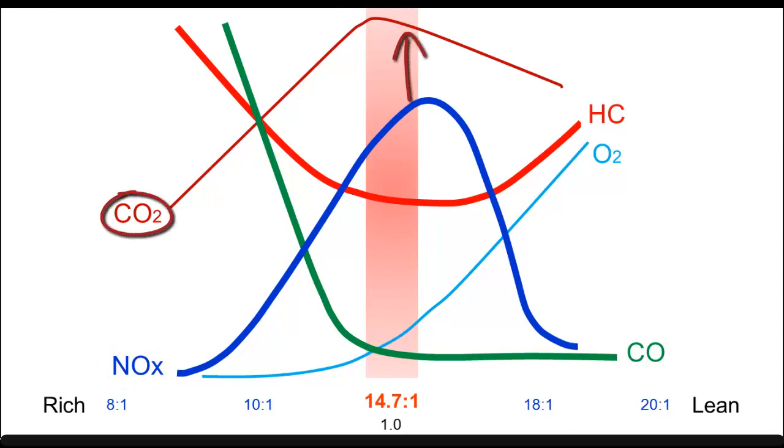This combustion indicator signals near stoichiometric mixture. Oxygen at 2.22% indicates slightly lean of stoichio. Lambda at 1.1 indicates slightly lean of stoichio.